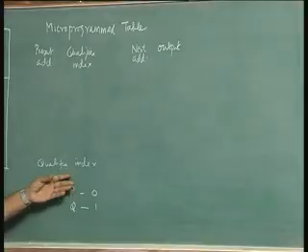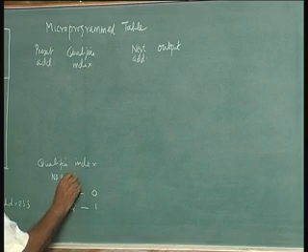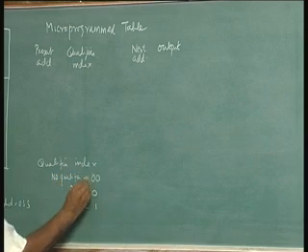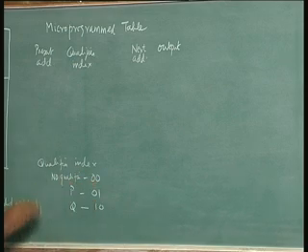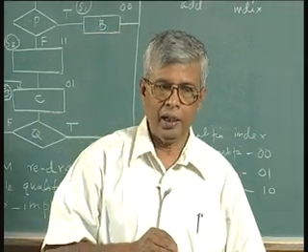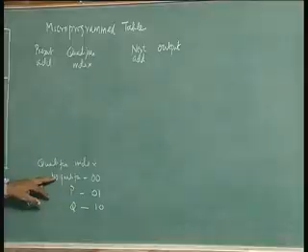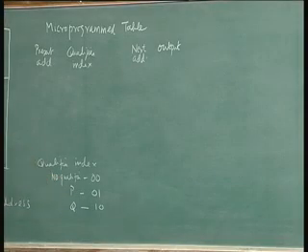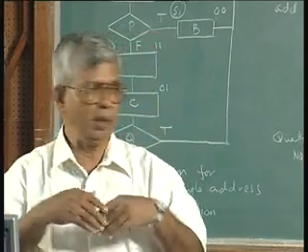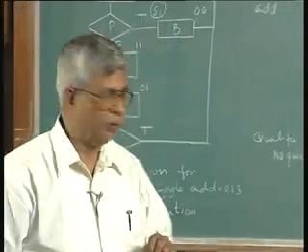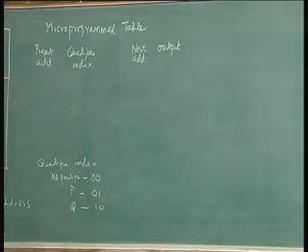So I am going to make 0 0 no qualifier, 0 1 is P, 1 0 is Q. This no qualifier condition was not required in the previous implementation, because I could always make one of those qualifiers the qualifier tested even when there was nothing to test, and make both the true address and false address the same. That way I did not have to worry about the no qualifier case, but here I have to worry about it. So, I have to put the qualifier index as 0, 1 or 2.